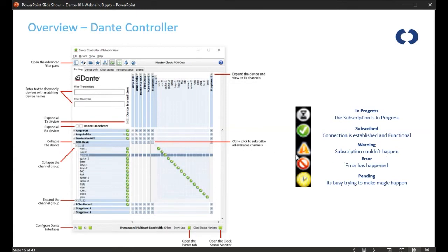There is the warning sign. Some of you might have seen this. It comes up typically if one of these units drops off. Let's say I'm transmitting here and this unit falls off the network. That little orange square comes up, which means the hardware is not there and it can't transmit the audio. But the beauty of Dante is that when that hardware boots back up, it will automatically do the subscription again, or it should, unless the network prevents it from doing that. It's very uncommon that the network will, but it auto subscribes back and it should go back to normal.